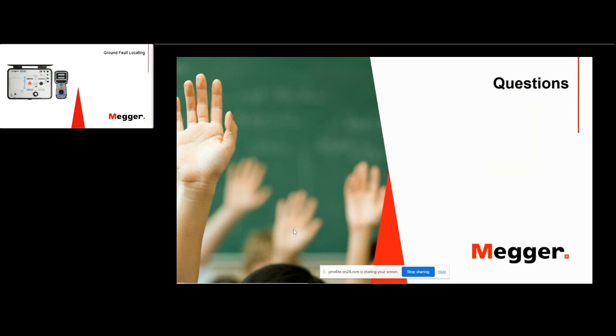All right, I think we have the first question here. Andy? Okay. Yes, it is quite a long one. I'll read it out. Some equipments are designed to have high inherent leakage current, which in normal operations will seem to be like a ground fault and trip the ground fault relays if the settings are not set above the threshold value. Is this type of equipment recommended safe to use? An example is the lift motor, and also does this inherent leakage prove detrimental during normal usage?